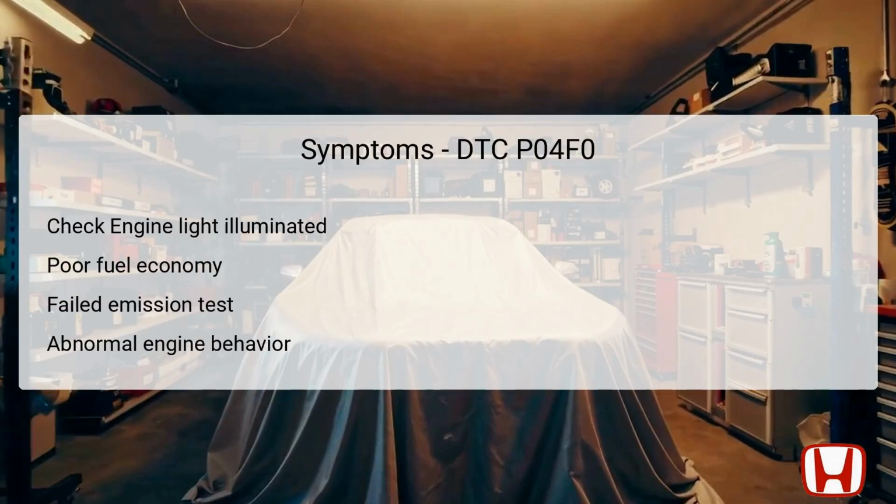When DTC P04F0 is set, the driver may observe several symptoms indicative of an underlying issue with the EVAP system. The most obvious sign is the illumination of the check engine light on the dashboard, prompting the need for further diagnostics. Additionally, reduced fuel economy may become apparent, as improper vapor flow can disrupt the optimal air-fuel ratio.